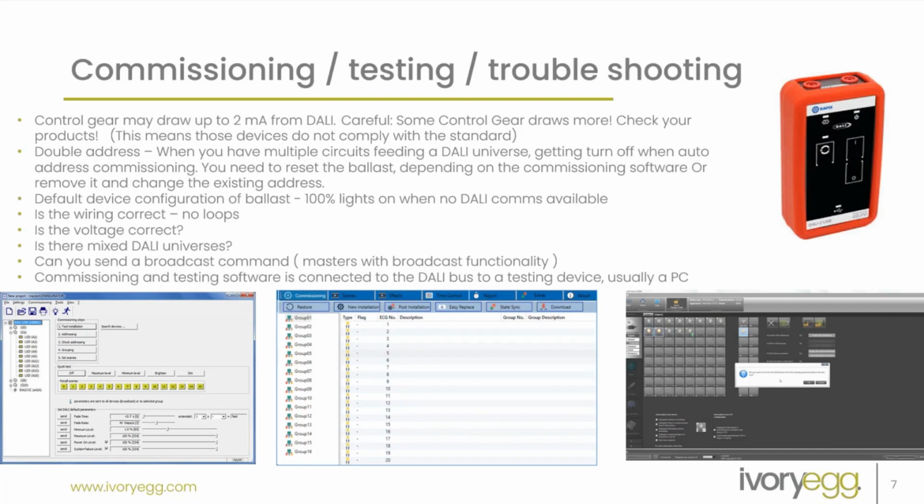And what we're going to look at in our little thing is there's a few different softwares to use. I know there's softwares that plug in through USB. Our DALI gateways, particular ones we're looking at the moment, we use the KNX bus to program the DALI networks. So we use the KNX to access the DALI side of the DALI gateways, and that way we can communicate. We don't need to plug into the bus or anything. Another advantage of that, if you're smart enough to set up remote access, then you can program the network remotely.